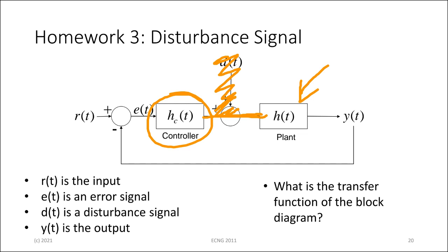Now that set value has to communicate to something in the plant, and it goes across some wires. But a lot of stuff happens in the wires. We just had a lightning flash up by me. That would send a lot of noise, which is little voltage spikes on the signals going from one point to the other, and the system has to be able to cope with that. So how we model that is by putting in another input that may happen along the way, and we call that a disturbance input, that is D here.